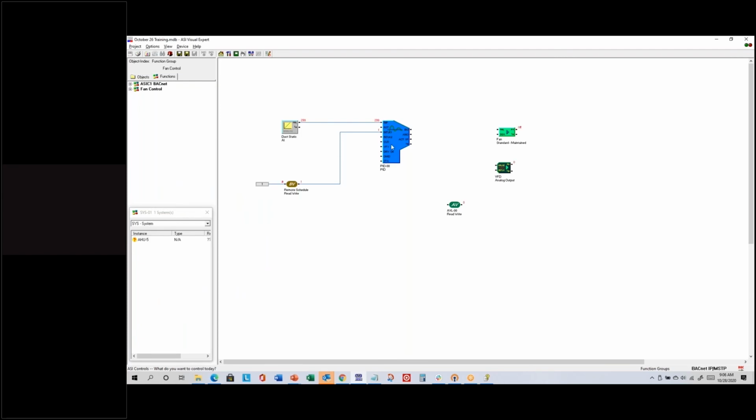Okay, so now that means that the interlock handle has been established at the PID icon, but now we can go into properties view. Actually, we can make the other output connection. So take the binary output BO and connect it to the VAL handle for the fan. And then take AO from the right side of the PID icon and connect it to the value for the VFD. I'm not going to connect the AV just yet because while we're programming, we'll look at some of the different settings, and that'll help us understand where we're going to connect this AV to.